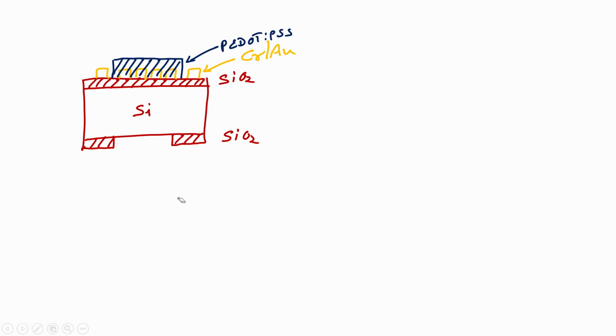When we dip this wafer in TMAH and KOH, what we will get? We will get a diaphragm like this, and this angle is 54.7 degree, right. So, what we got?